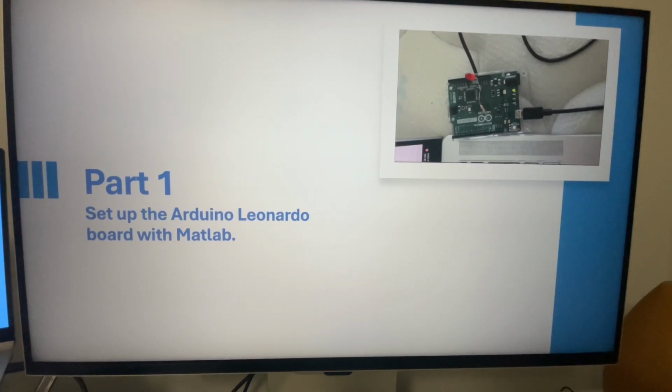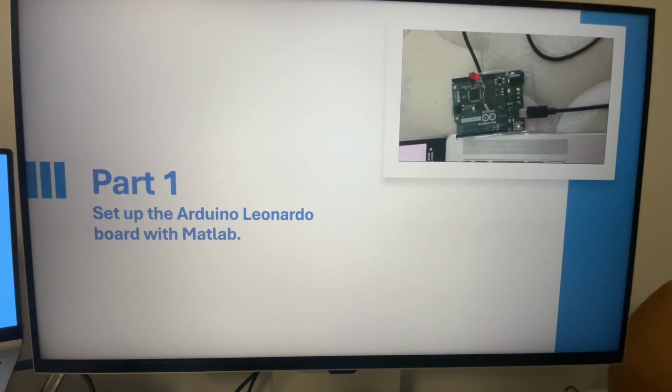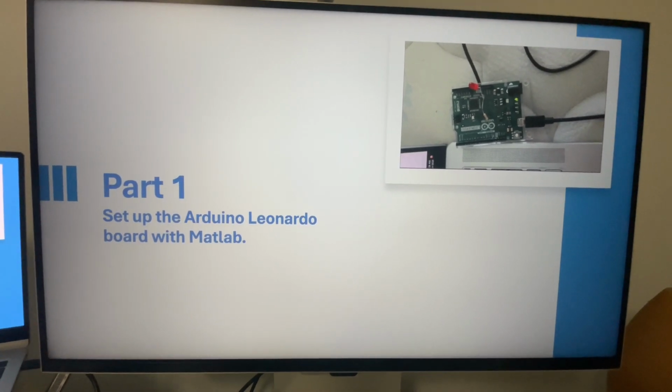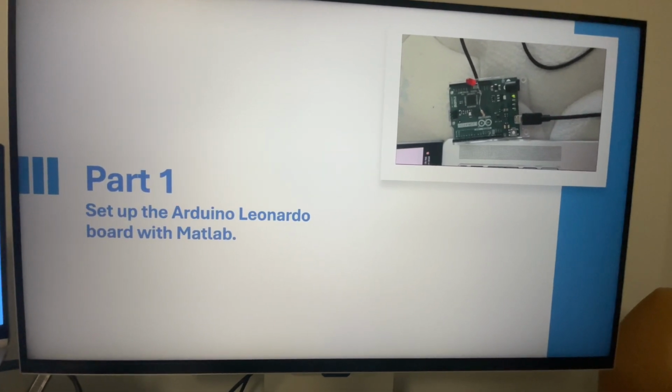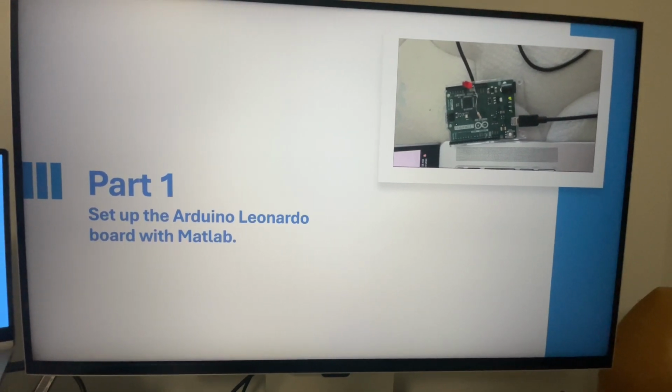We used a 1 kilo ohm resistor and connected it to the anode of the LED, with the cathode connected to the ground. After running our code, we saw the LED blink in a pattern for the letter O.